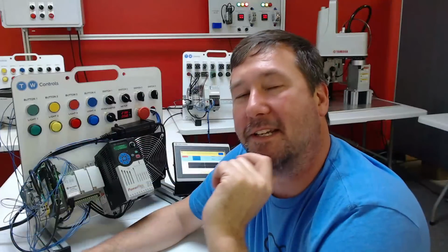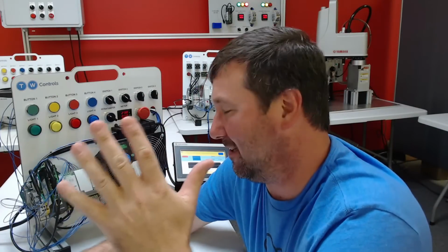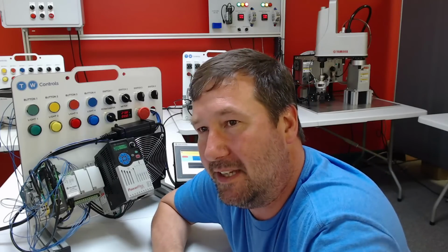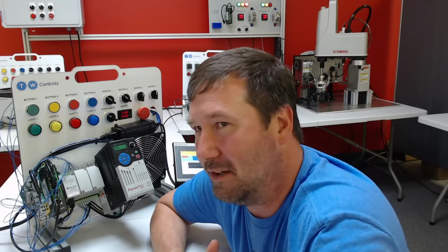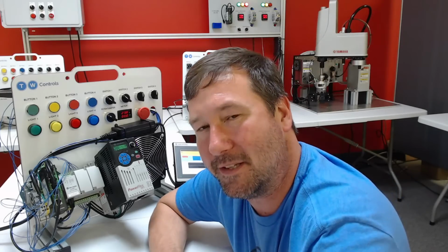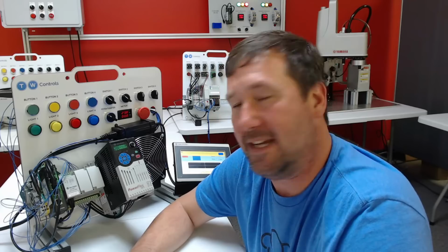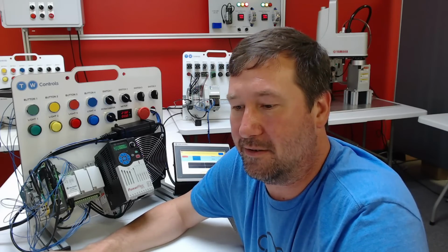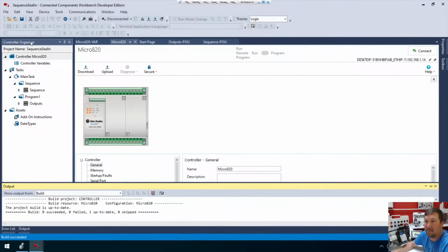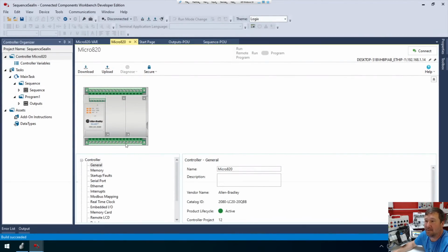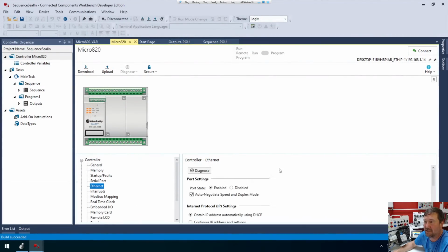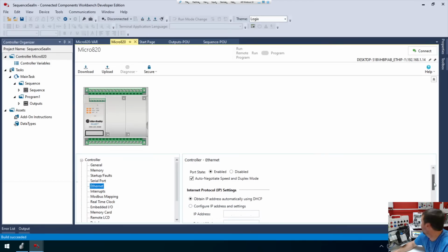If you have watched any of my videos, I always tell you the one thing about Connected Components Workbench, and I think they could work this a little better, although there is a warning there, but it's not really clear, is when you create a new program, it enables DHCP by default. And if I go here to my controller properties, and I go to my Ethernet configuration, I just downloaded a PLC with DHCP enabled.